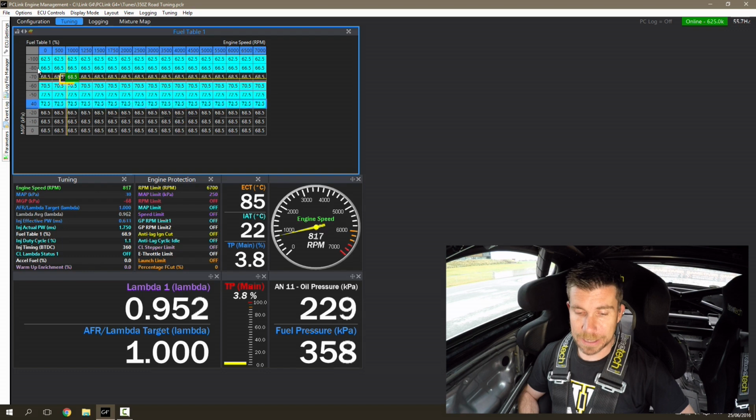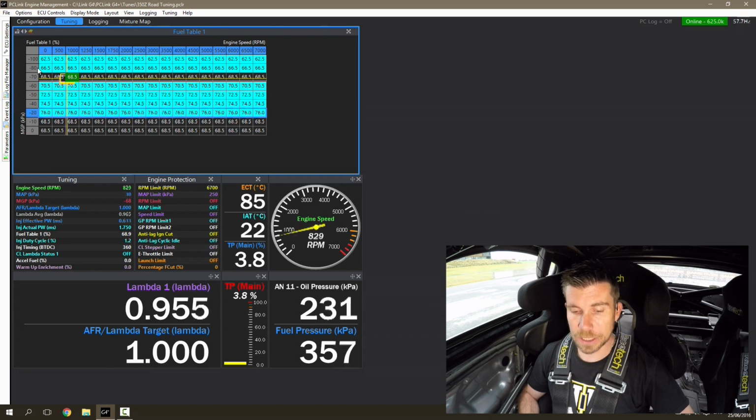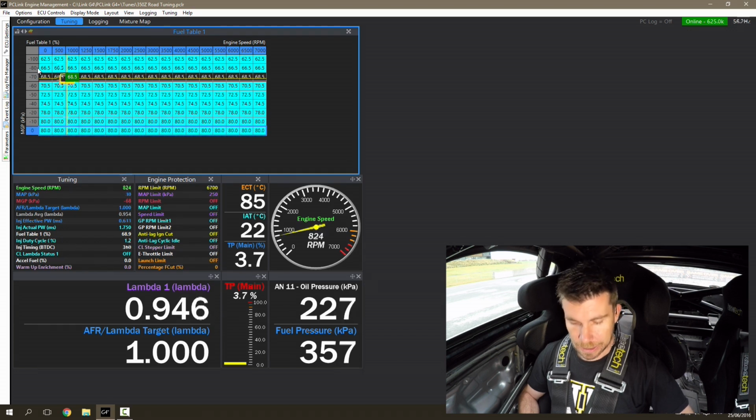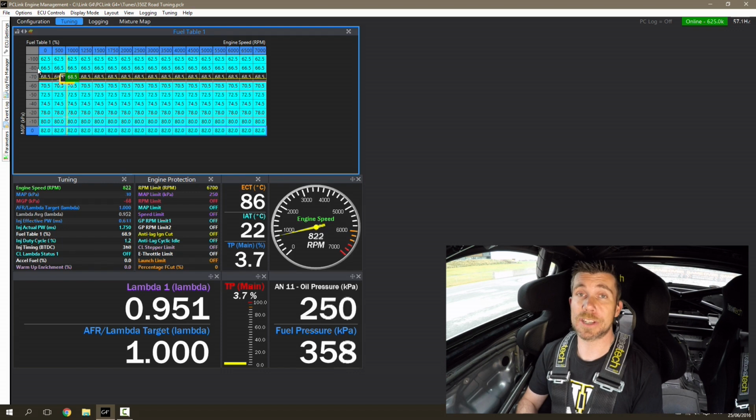All we're doing is making a guess that's hopefully going to get us a little bit closer to the correct operating air fuel ratios as we start tuning. And of course, it's going to be very easy for us to correct any errors we find in this table once we actually start running the engine, but this should at least give us a table that's a little bit closer to correct than if we have a flat table.